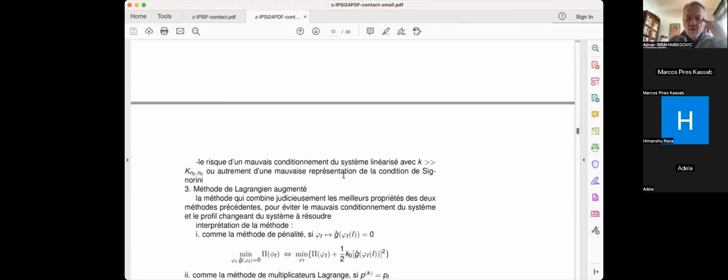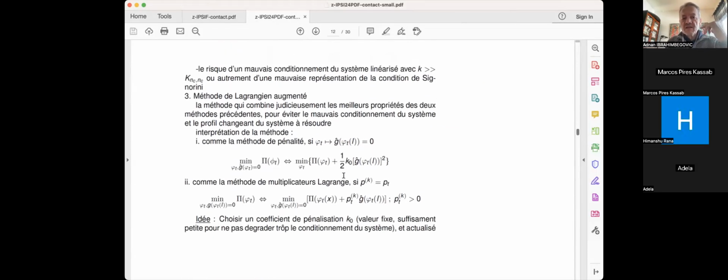So what people finally did is the following, called the augmented Lagrangian formulation, which, by the way, you could also use for plasticity and many other things. You choose a stiffness which is good enough for this obstacle, so that you have a good conditioning of your tangent stiffness. So this is K0, not the real one that would really be required. Then this is so-called penalized, and then you also dualize. That means you go to the Lagrange multiplier method.